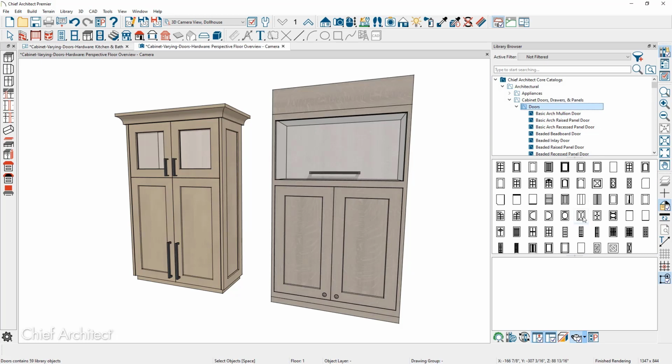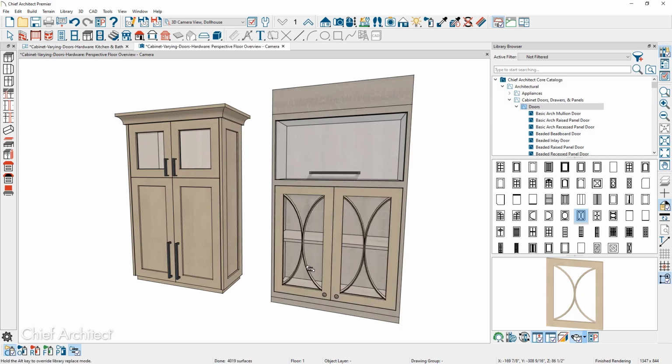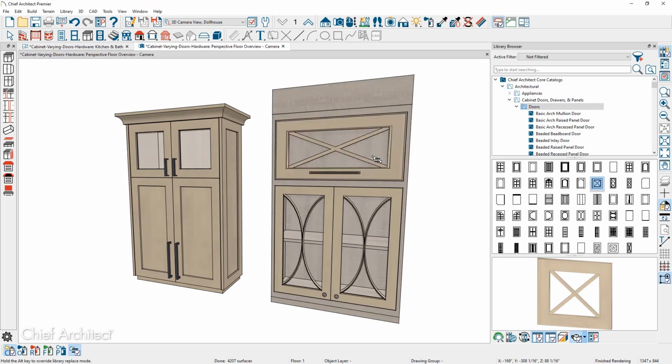Once you locate the door style, go ahead and select it. Make sure the scoping mode is set either to the object, which would be the entire cabinet, or component mode, which would be the face item. You can then apply the door style. Notice how my cursor changes to the replacement icon. Select the door style, come over, click, make sure your cursor becomes the replacement icon.